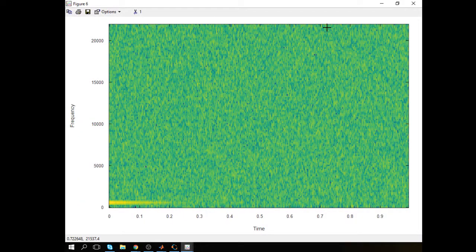If you take a smaller window size, then basically you will start having fewer pixels on the frequency scale. But if you take too big a frequency resolution, then basically you are losing on the time, unless you are doing more overlapping. Okay, but as I said, this is a picture, and you have some parameters to tweak it so it would look nice.